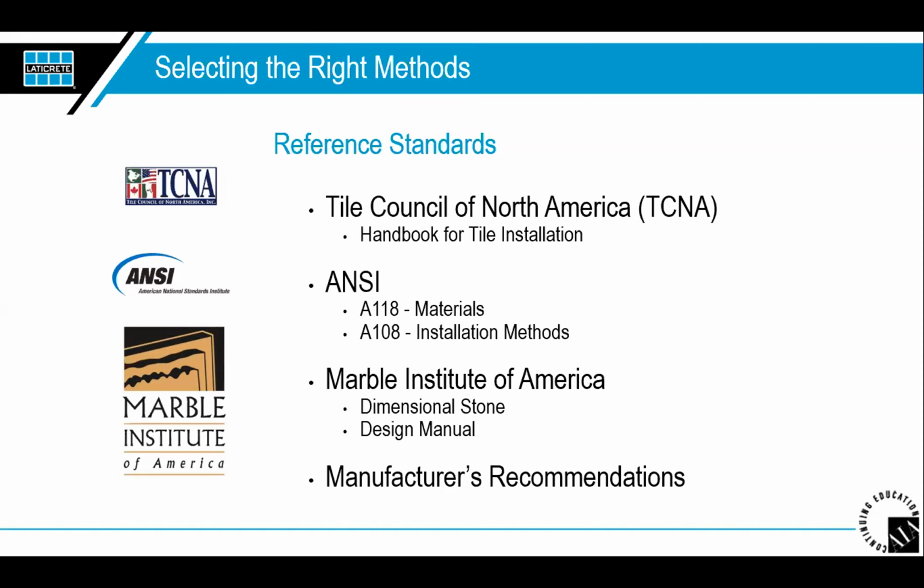Again, manufacturer recommendations from the installation material side can also specify, and I'll call it trump, any standards, where they say, hey, we are going to warranty this product even outside of its traditional standards that may be set by the TCNA. So always going to the manufacturer's recommendations is going to be a big deal when we're talking about the tile installation.